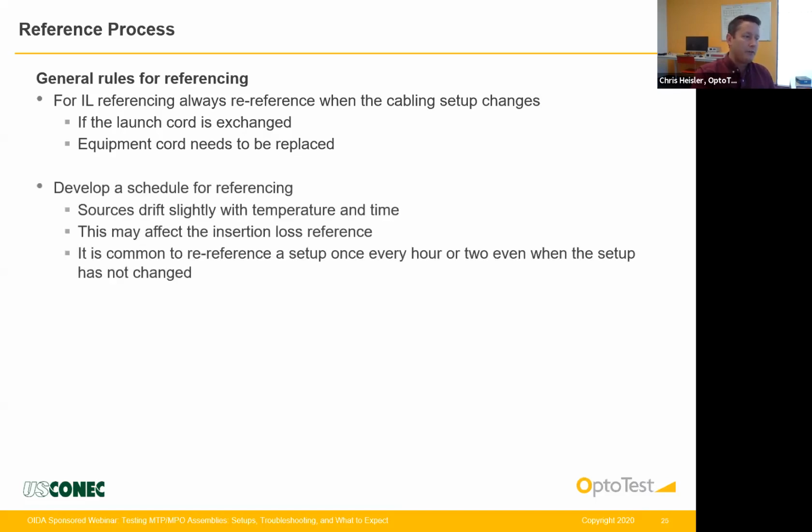Develop a schedule for referencing. Sources will drift with temperature and time, so this may affect the insertion loss reference. It's common to re-reference a setup once every hour or two, even when the setup is not changed.